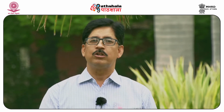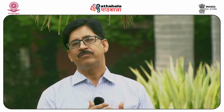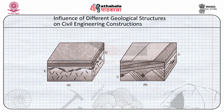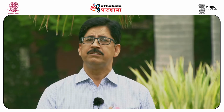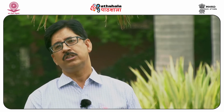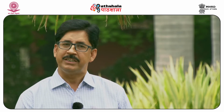Along an unconformity we have to be very cautious, because across the surface you will have two rocks of different kinds and ages, and they may have different deformation structures. Also, it is very common to have residual conglomerates and paleosols along the unconformity surface, which are very weak material.